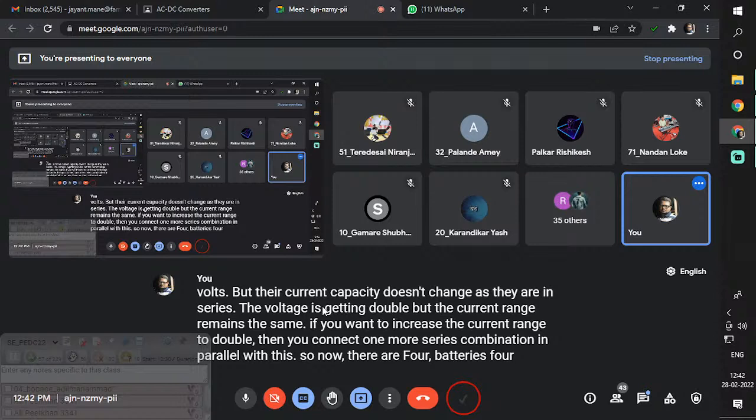If you want more power and higher voltages, in that case you have to use AC to DC conversion. Then one may say that okay, there is another option available. We can use DC generators. No doubt we can use DC generators to get whatever DC voltage we want. This is the same case as when Edison developed the DC system. He had a set of generators. Now the problem with a generator is it needs a prime mover.